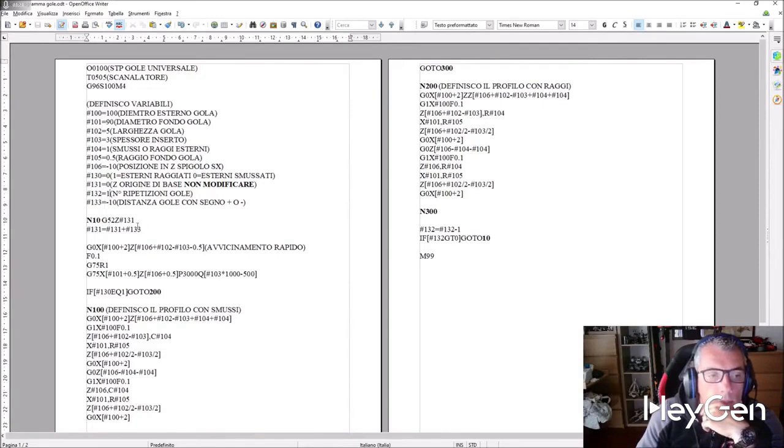After that, I'll set my origin by establishing an origin shift, which will initially be a shift of 0 mm. Under my origin shift, I'll modify my 131 by adding the origin shift to it. So I'll set a safety distance, a rapid distance of 100 for the outer diameter plus 2 mm, and Z will be a count that ensures there's 0.5 mm of excess material on the right side.